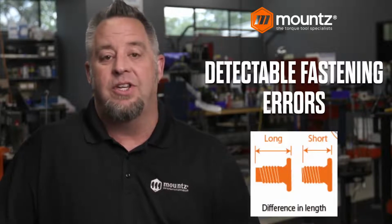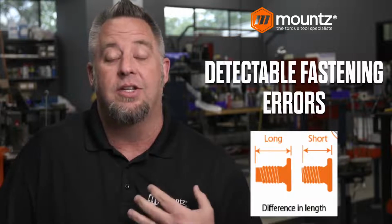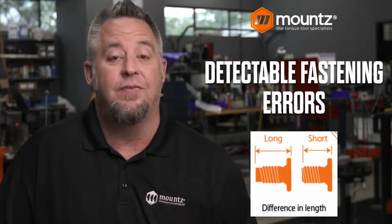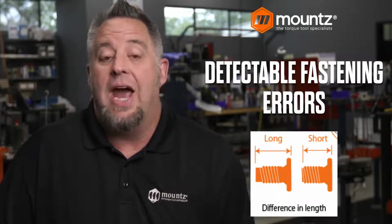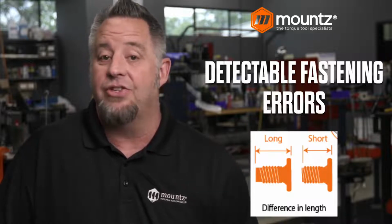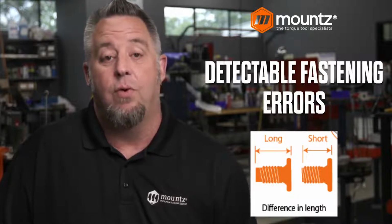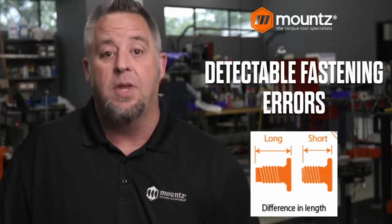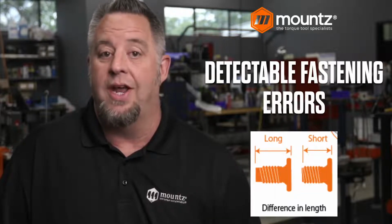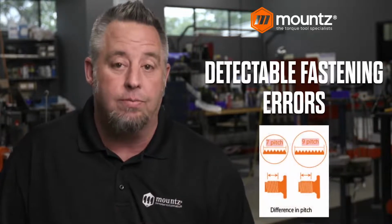So what are some of the detectable fastening errors that we can catch with a screw counting type of implementation? First is going to be the different lengths of fasteners. If you have the same thread pitch and the same size of fastener, but they're just different lengths, we can ensure that the correct fastener is used for that particular application based off of the length. If we use one that is too short or too long, we'll be able to detect that type of error.